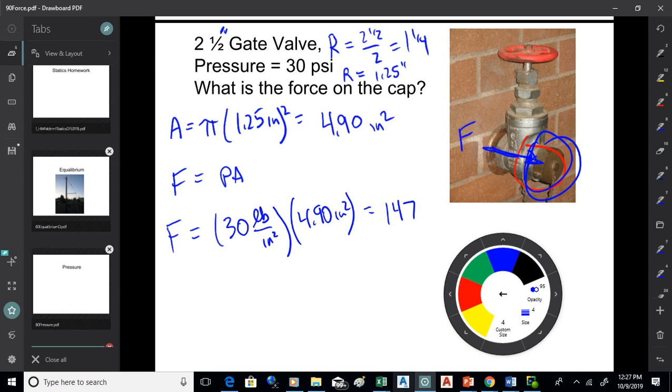So if you call them up and say, I got low water pressure, they're going to come. They're going to shut that angle valve on the meter. They're going to pull the meter. They're going to put a pressure gauge on that valve and open it back up. And they're going to read pressure, okay? And if it's 20 psi or higher, they're going to tell you to hire a plumber. And if it's less than 20 psi, they're going to fix it, okay? That's how that works. So 20 psi is a minimum standard for city water, typically. Okay. Now that is one thing.